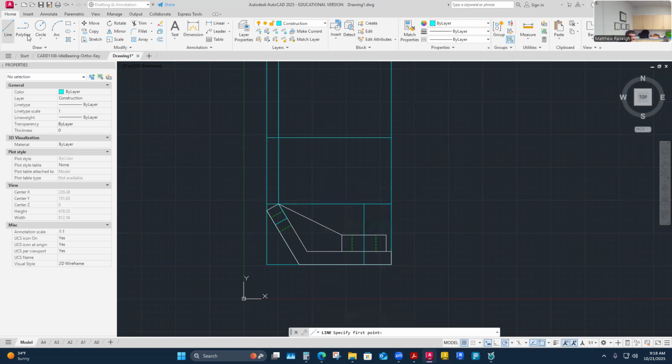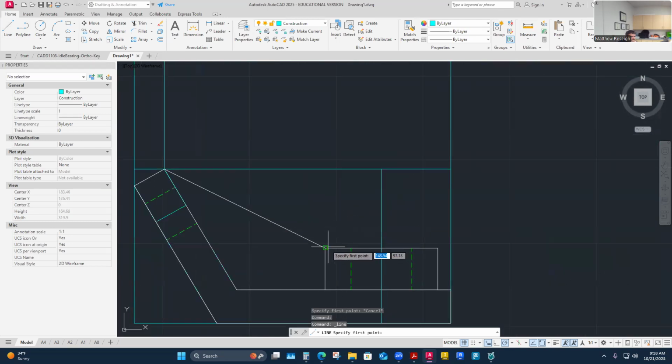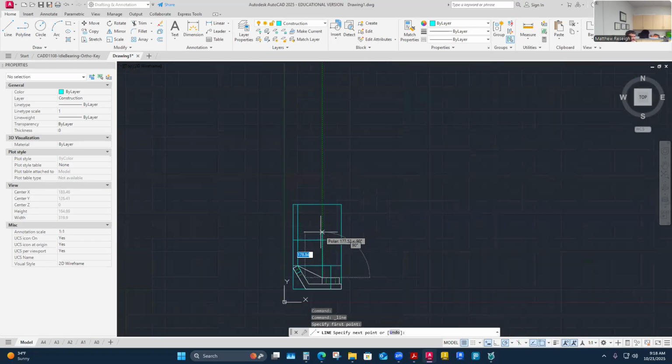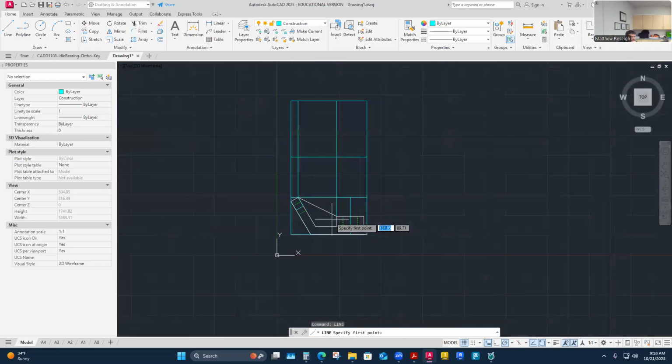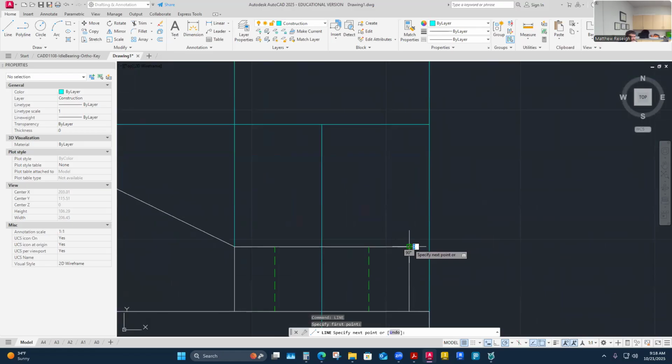So I'll project a lot of these features, these points to points. I've already got those two points. I'll come back to the hole in a second. Maybe I'll worry about the visible line features first up here. So I'm going to project this one up too.